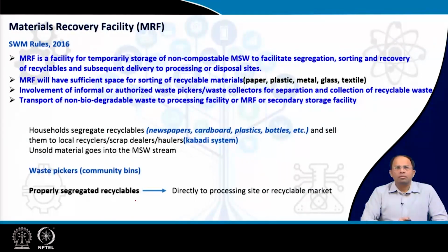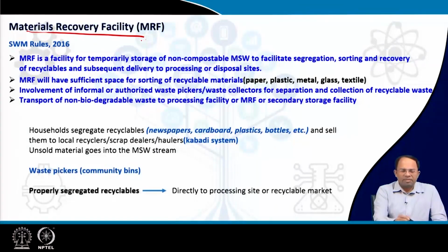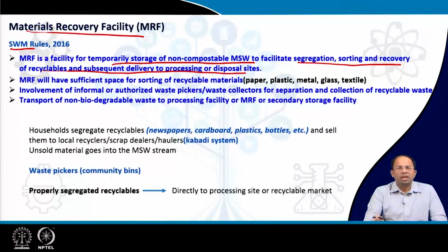So, as per the Solid Waste Management Rules 2016, every ULB has to set up material recovery facilities. An MRF is a facility, as defined by the Solid Waste Management Rules 2016, for temporary storage of non-combustible MSW to facilitate segregation, sorting, and recovery of recyclables and subsequent delivery to processing or disposal sites. So that means MRFs are areas where we don't process it. Sometimes we can process it, but usually it is for segregation, sorting and recovery.